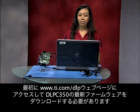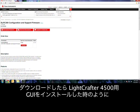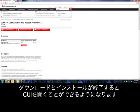To begin this process, you have to go to ti.com/DLP and download the latest firmware for the DLP C350. Once you've downloaded the firmware, you can install it in the same directory as you've installed the LightCrafter 4500 GUI. After you've downloaded and installed the firmware, you can open up the GUI.